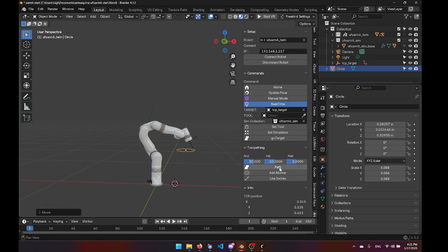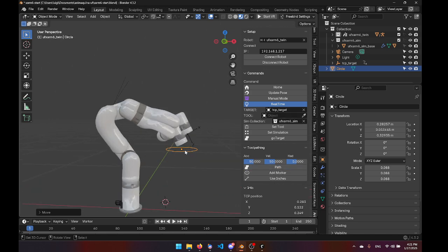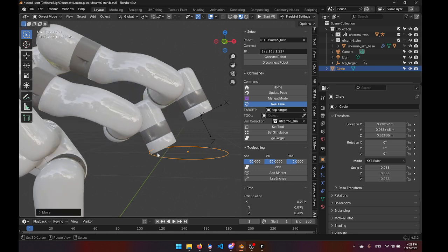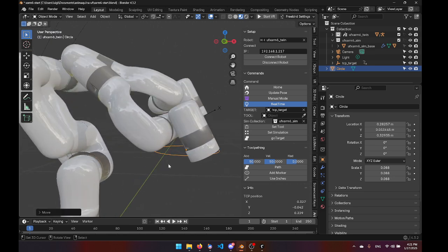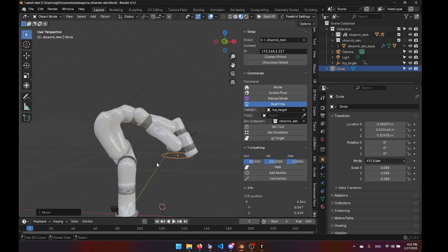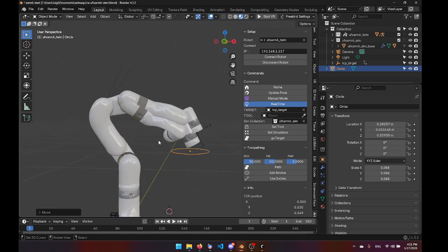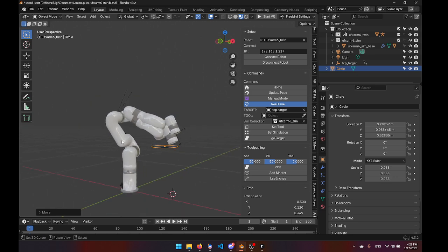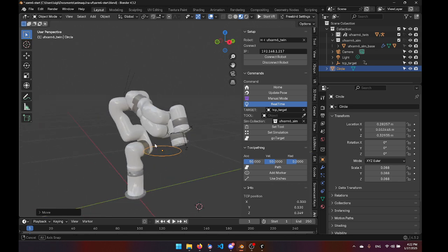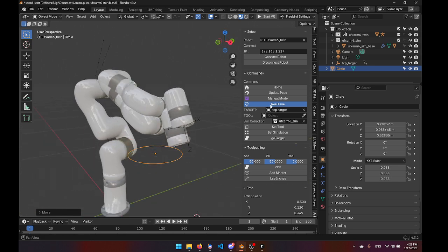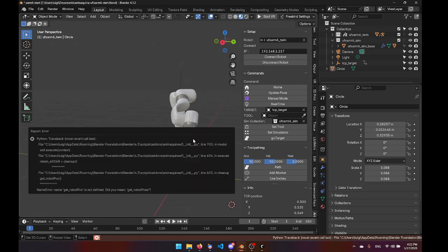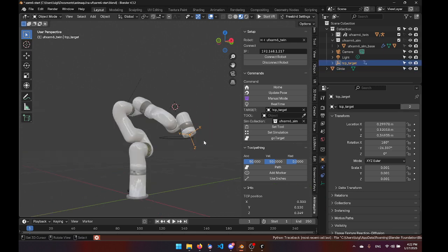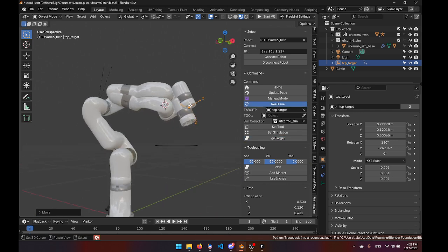And then I'm going to click on path. And this should allow the robot to go and trace that movement. In this version, as you can see, it's difficult to simulate safety boundaries and things like that. So just be careful and worry about the reach and the limitations of your cell and your robot. If we turn off real time, it will update again. And we can go and simulate move again the robot and see it update.